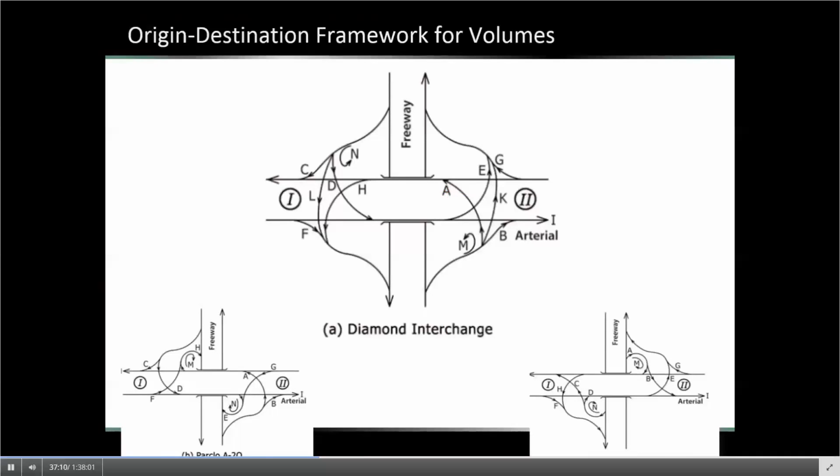So depending on the configuration, the movement stays the same, but the way it is integrated into the system of intersections may change. And that impacts the inputs needed: origin-destination volumes across the interchange or cluster intersection system are needed as inputs. All the outputs are also reported by origin-destination pair, where it's broadly speaking a left turn or a through movement that goes through any and all intersections that are part of the distributed system.